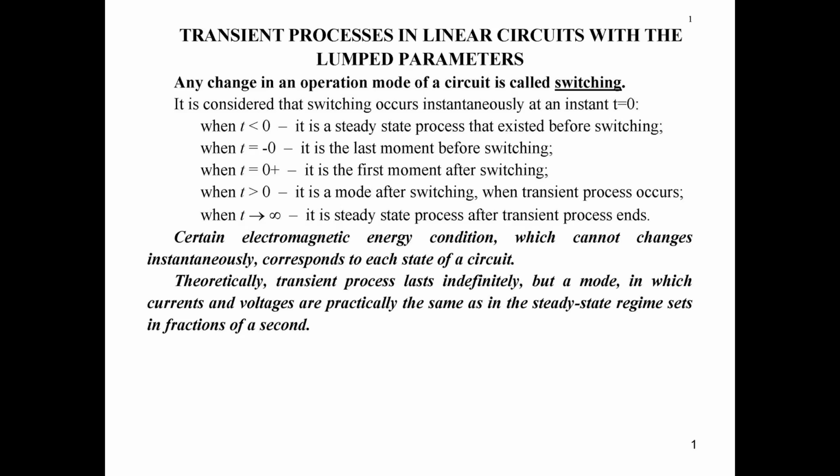So we may consider that in each point of the considered electrical circuits parameters of electromagnetic waves are the same. In such a case, we can consider that these resistances, inductances, capacitances may be presented as lumped parameters, not distributed, as when the length of the electromagnetic wave is less than the linear parameters of circuits, and in two different points of this circuit we may obtain different levels of electromagnetic fields.